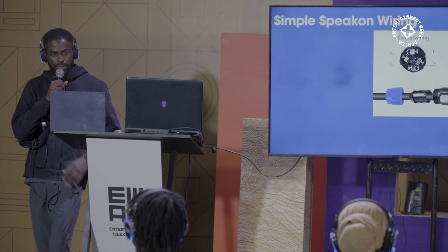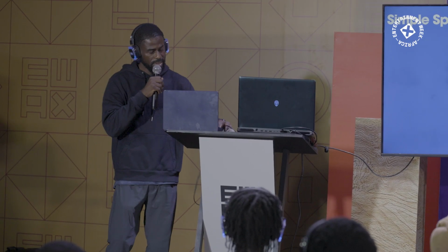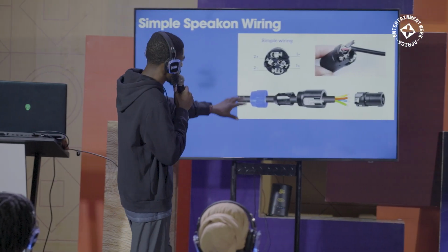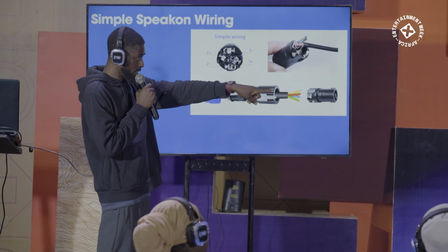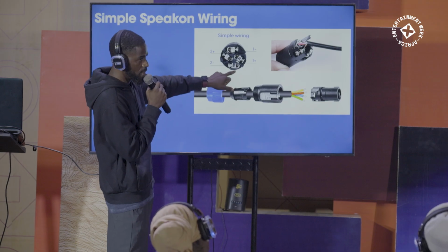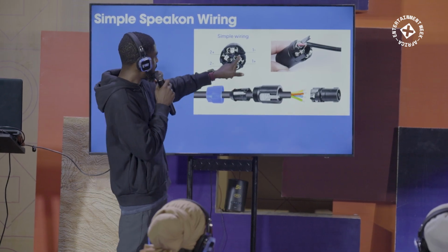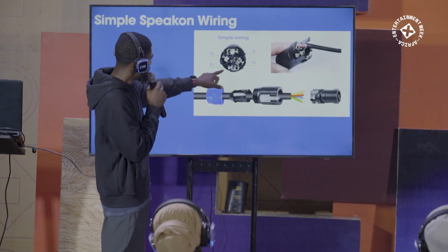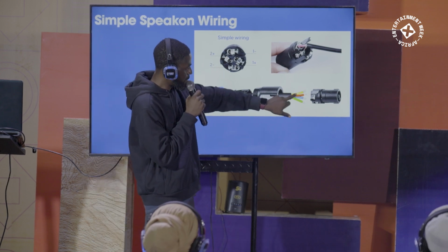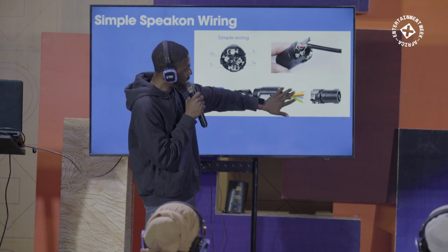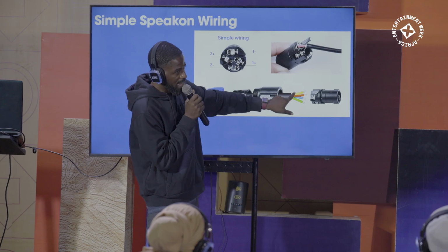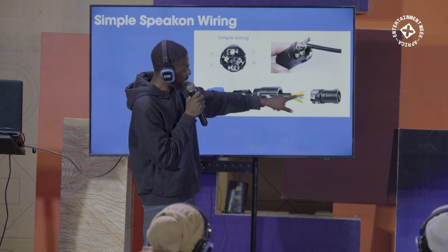The next is your speaker, which is your speaker cable. The same thing is applicable to your speaker cable. When you open up the connector of the speaker cable, you will see 1, 2, 3, 4. In it, you have -1, +1, -2, +2. As you can see, these are your cables with different colors. They are usually color coded. Usually the lighter cables are on the minus, and the deeper, like red, are on your plus.